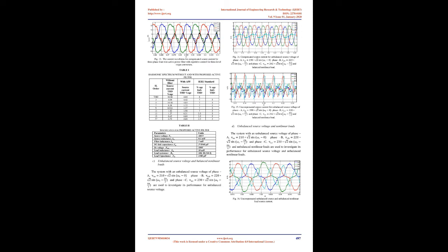Fig 4. Comparison of open-loop Bode plot for conventional and modified RC controller. As one observes from Fig 4, comparison of open-loop Bode plot for conventional and modified RC controller, and Fig 5, comparison of sensitivity function for conventional and modified function, the modified sensitivity function-based RC controller has higher open-loop gains and deep notches at targeted harmonic frequencies. This provides better performance for the RC controller as compared to the conventional one.